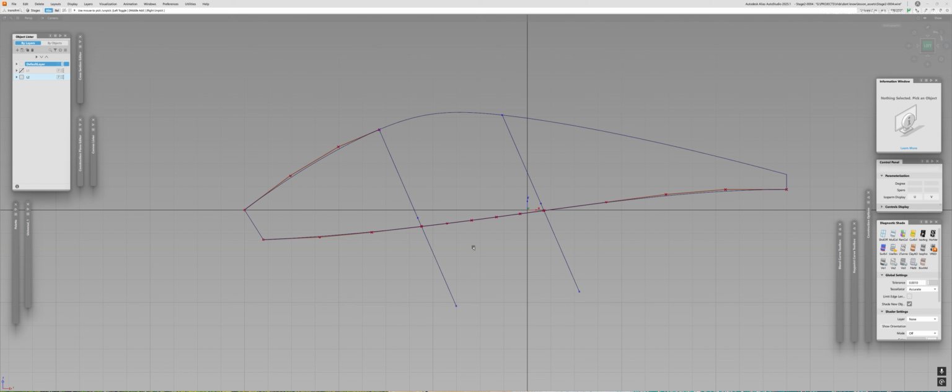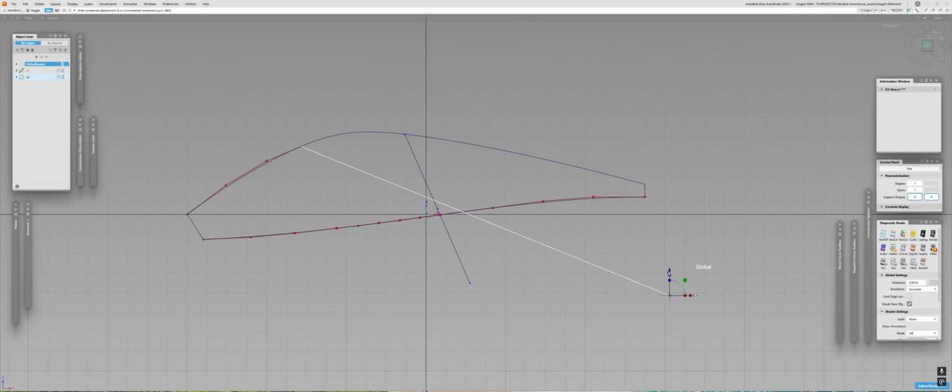Why do I need a perpendicular edge? Well, in general, you kind of don't, but the angle between the two surfaces which you want to create a continuous transition for, they better be at a 90-degree angle. If they aren't, Alias can handle it just fine, but to some extent. So if the angles are too wide or too narrow, you may have problems, right? So if I do something like that, for example, right? I'm exaggerating things, but you get the point, right?